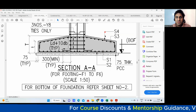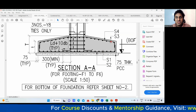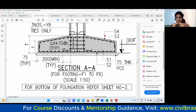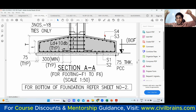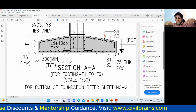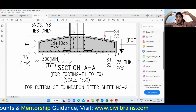Similarly on the top, this S4 is your distribution bar and S3 is your main bar. Okay. Sorry, S4 is your main bar, because see, bottom shorter span, bottom longer will come. Again, in top, shorter span, and inside that will be your distribution bar. The main reinforcement will be at the top, but in the bottom, the main reinforcement will be in the bottom.